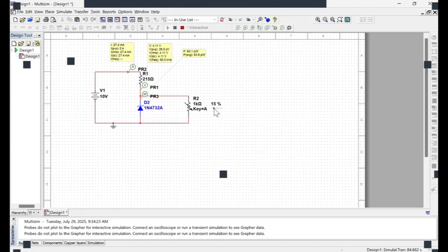so it could keep the voltage across the terminal equal. So let me go toward like 50. Now you can see the current is passing the value that we aimed for. So probably the 215 is not safe enough. We need to apply a safety factor, for example 5 or 10, to make sure we are good. Don't do 10 because we are going to fall below the minimum. You have to choose a scaling factor for the safe resistance in a way that we are between the minimum current and maximum current.